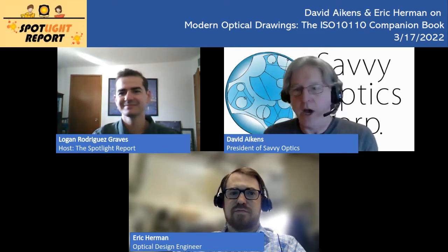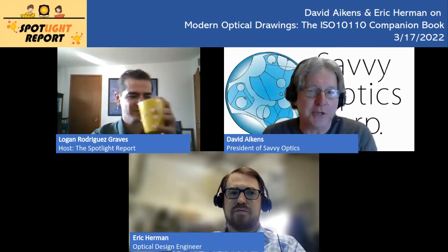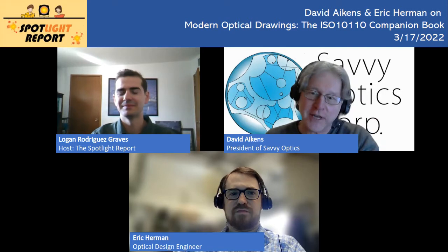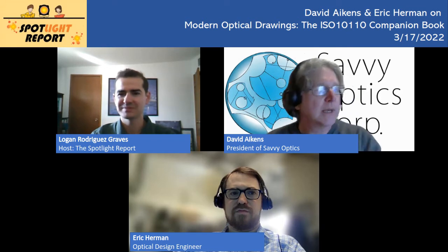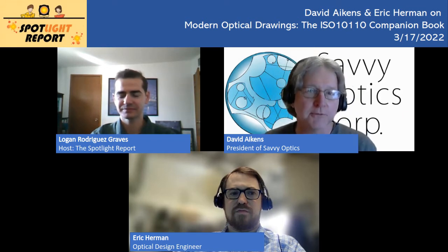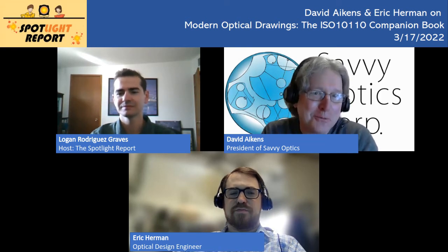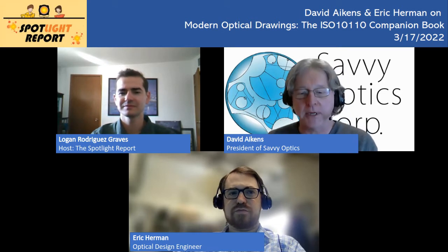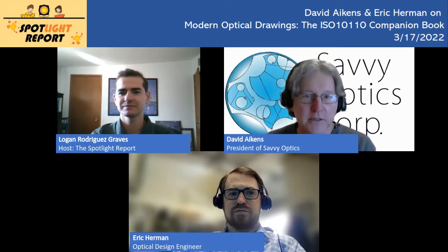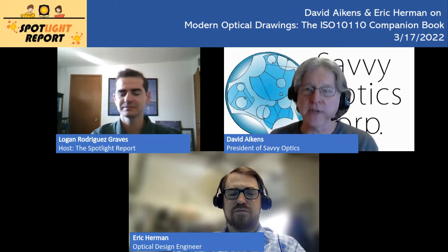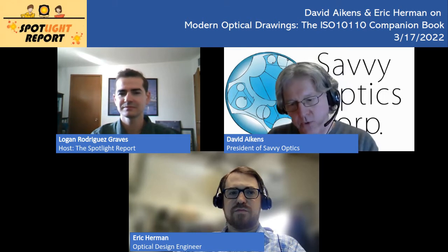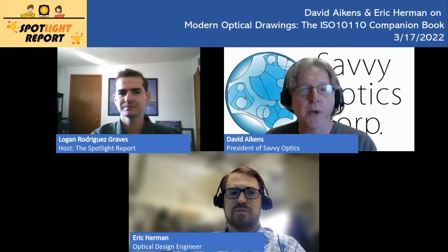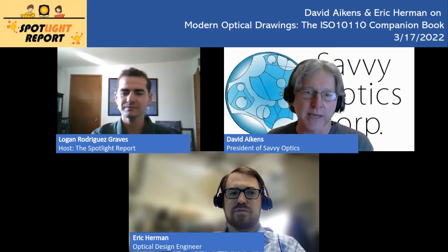But in the optics world, it's not even a view, it's actually a cross section, right? So we have this cross-sectional view, and that's just traditional throughout optics, both in Germany in the DIN 3140 system and in the United States in the ANSI Y14.18, or even before that, the MIL standard 34. They've always allowed this cross-section view as the only view if the optic is rotationally invariant, and there's no need for a second view. You can explain everything in that single picture. So that's one of the aspects of chapter 1, where we go into what the format of the drawing actually has to be.